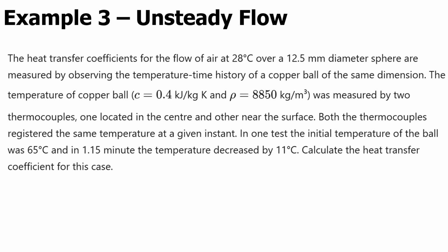Interestingly, the temperature of the ball was measured by two thermocouples, one at the center and one near the surface, both registering the same temperature at any given instant. In a specific test, the initial temperature of the ball was 65 degrees Celsius, and after 1.15 minutes, its temperature dropped by 11 degrees. Our objective is to calculate the heat transfer coefficient for this particular case.